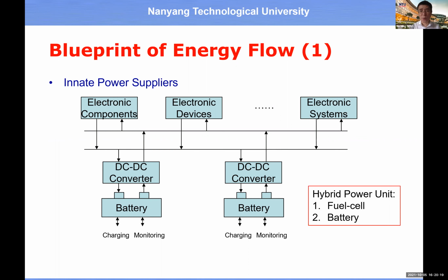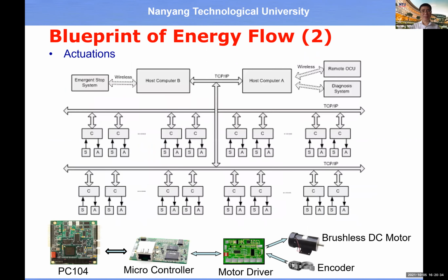In particular, we must separate the supply of power for actuation and the supply of power for the sensor or computing unit. This is why we need this type of distributed power supply system.